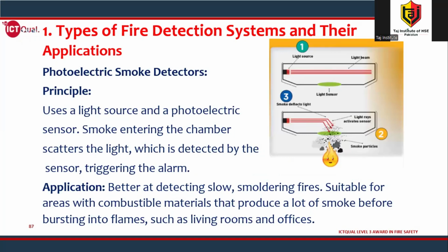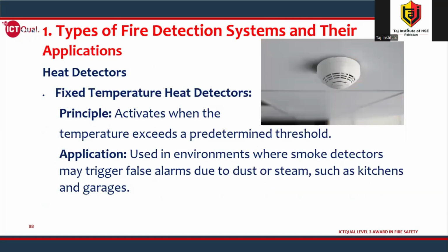Photoelectric smoke detectors. These are another type of detector. Photoelectric means it uses a light source. Smoke entering the chamber scatters the light, which is detected by the sensor, and it starts the alarm. Application: better at detecting slow, smoldering fires, suitable for such areas.